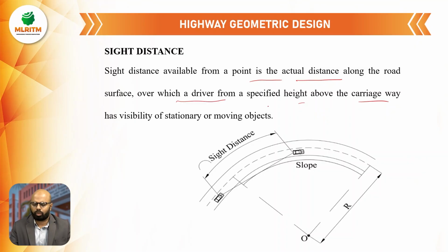So what is the specific height? As per IRC, we will be taking driver height as 1.2 meters, and if you are talking about object height, it is 0.15 meter.